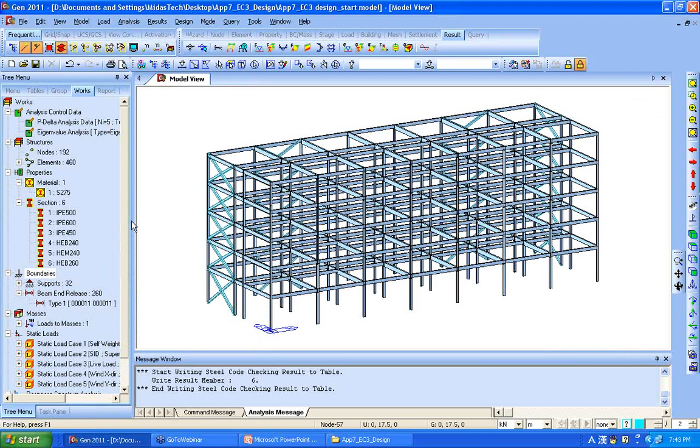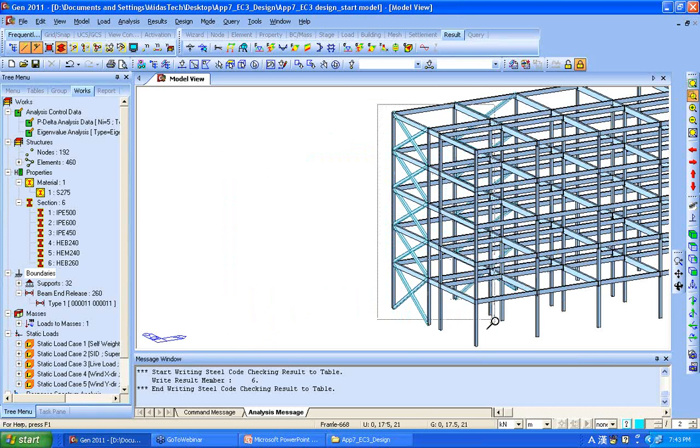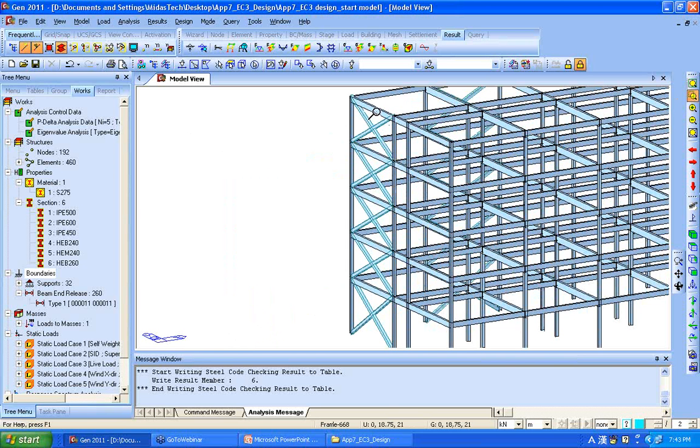And I will explain about the bracing. As you know, this is the bracing. Nonlinear analysis using the tension-only elements does not have any relative result with the linear load combination. It is because the stiffness of structures that is used in dead load analysis is different from the wind load analysis.